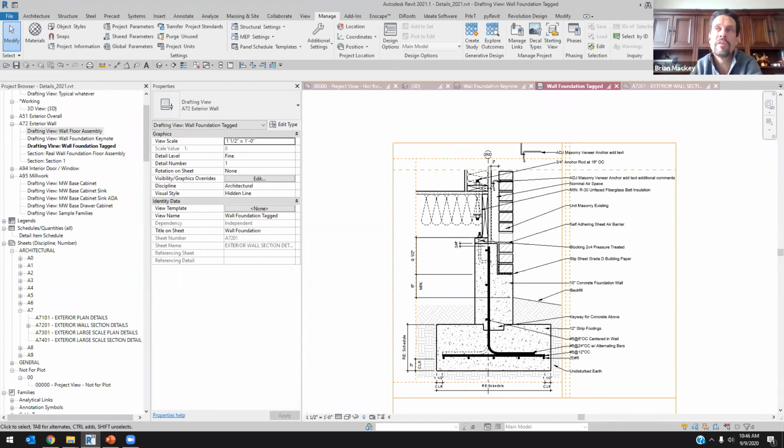But that is an issue in Revit. It's just a Revit issue. So if you are copying and pasting multiple times, you're more than likely going to get multiple different detail components. So to me, it just depends. I have some clients who keep zero detail items in their template, and they nest or link everything in through a linking process that I've come up with. I have other clients who say, no, we load them all into the project and then we delete what we don't need. So there's not a real great way for that. I think it's just going to be one of those things once you start getting inside of there.